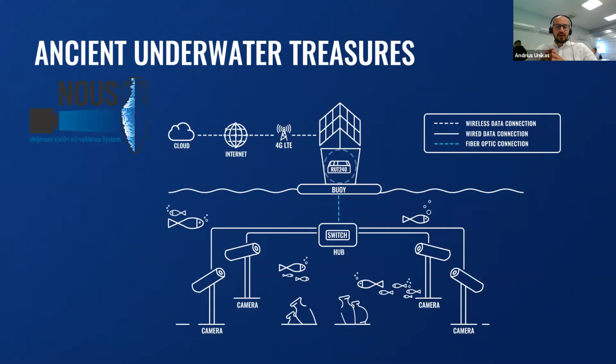Onshore or placed on a buoy is a fully autonomous photovoltaic panel system and batteries that provide electricity to the solution. There is also an RUT240 router providing internet via 4G network, which further travels underwater through the fiber optic cable. The underwater section consists of 5 cameras and a switch. All cameras send video streams in real time for processing.